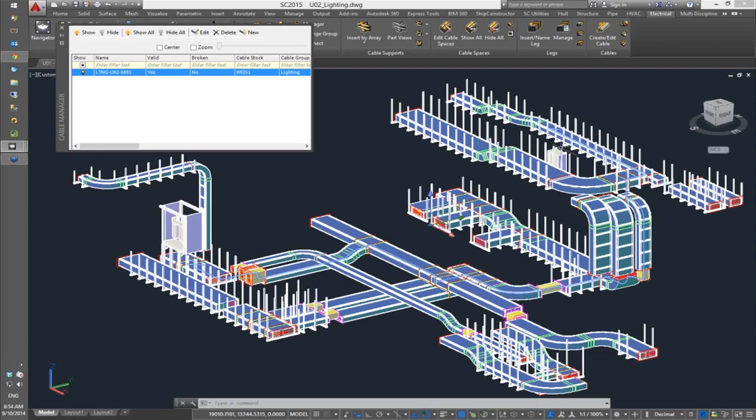So now we've gone, I'm not sure it's quite full circle, but we've covered the gamut of working from building up the wireway model, defining some of the physical elements, constraining the wireway for EMC, and then actually routing cables into the wireway. So that's the end of the demonstration as far as I've got it.